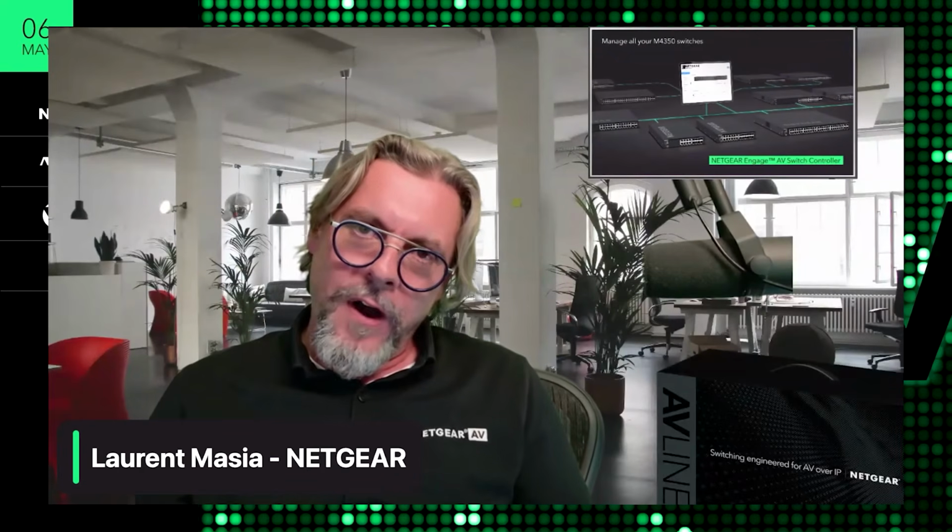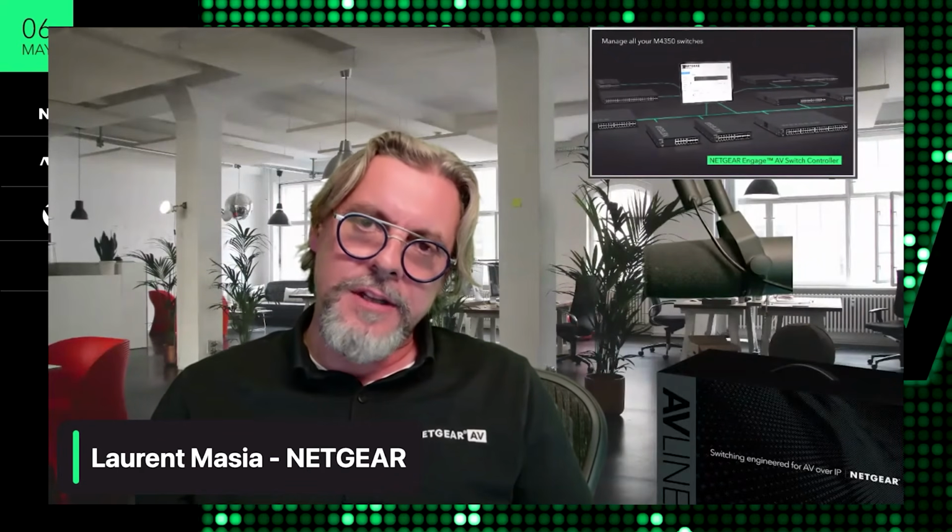All right. So I have one from the same John actually. 4K images, videos, I guess, can utilize upwards of 18 gigabits per second. SDVoE is using 10 gigs, so I would presume some level of compression is at play. And I can start the answer by saying that the HDMI overhead is not in the equation, so it's not 18 gig for 4K 60 4:4:4. It's far less than that, approximately 13 gigabits. And yes, there is a very light compression, but I'm sure Melissa can't wait to tell us how fast and seamless that is.